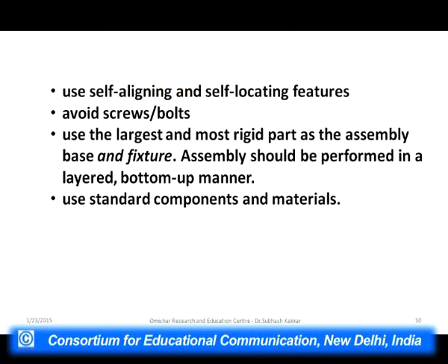Use self-aligning and self-locating features. Avoid screws, bolts, etc. wherever possible. Use the largest and most rigid part as the assembly base and fixture. Assembly should be performed in a layered bottom-up manner. Use standard components and materials as far as possible.